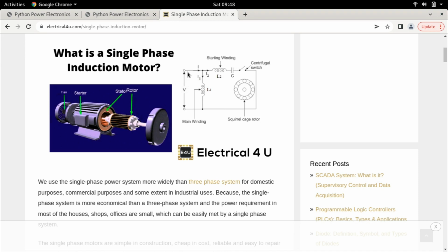Now, besides that, you see there are two windings. Again, forget about the second winding because we haven't talked about it yet. The need for the second winding will come later. For now, just assume that we have one single main winding, right? So this connection here goes into energizing the stator winding, which is this inductance L1, that represents the self-inductance of the stator.